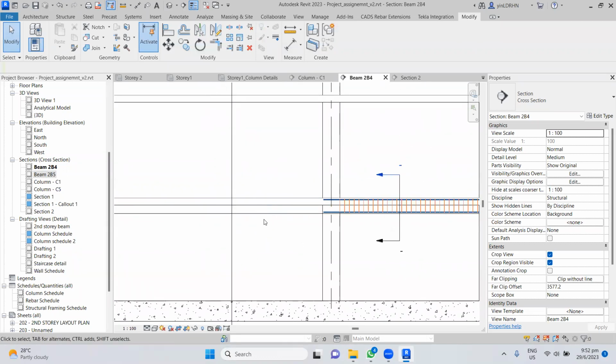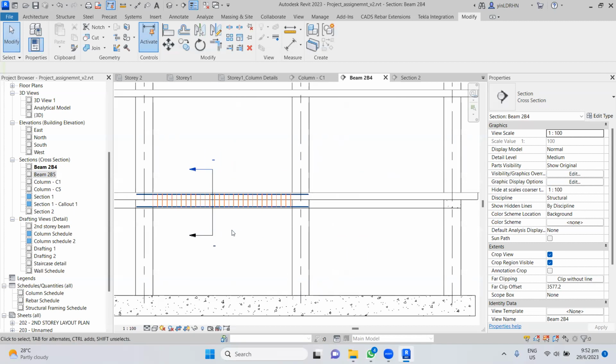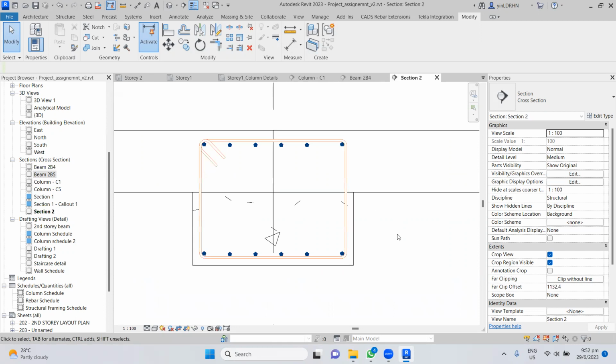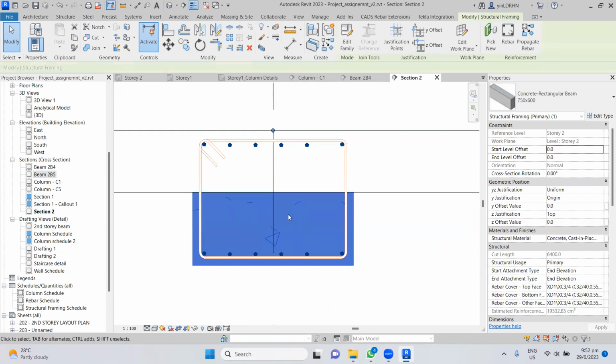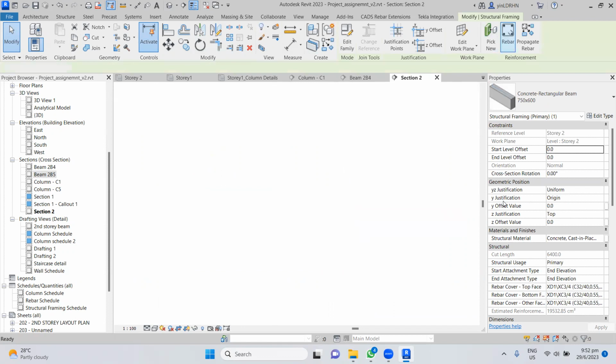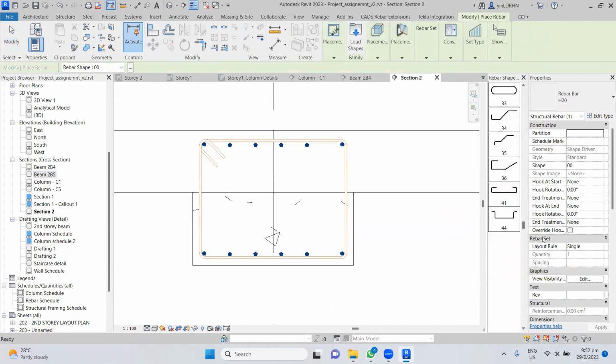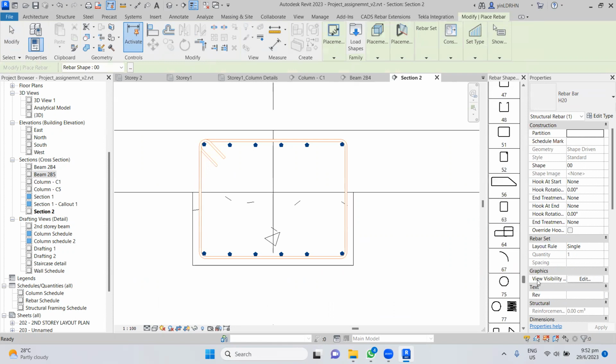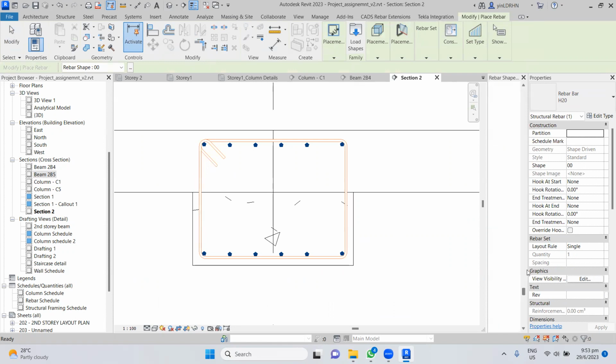So now if we add another rebar here, another beam, right? Then you can lap it here, right? Okay, so one beam we produce this way. Understand, right? So basically you have to go based on the sections and plans. Okay, so if you want to add another link here, the standard section covers only the outside, they don't have the inside, I think. So we can double check whether they have the link inside or not. I think they don't have.